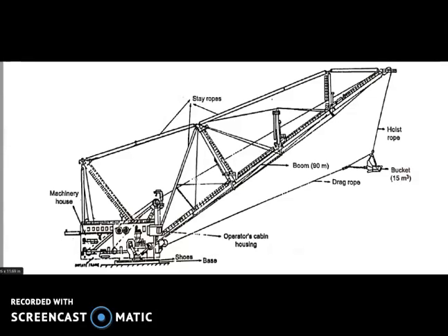Next is the long length truss boom. These are made of tubular framework. The overhung boom is supported by stirrups, which are supported by an A-frame. This type of boom is used in a 24x96 dragline. Tube frames of the boom are filled with an inert gas, basically nitrogen, up to a certain pressure. All the tube pressures of the boom are internally connected so that leakage at any point will affect the pressure of nitrogen for the whole boom and thereby automatically provide a signal for immediate inspection.